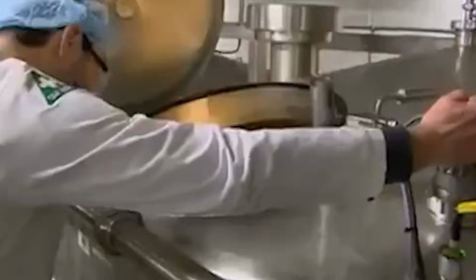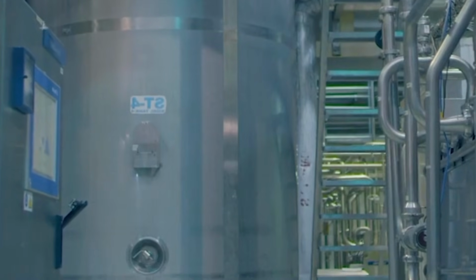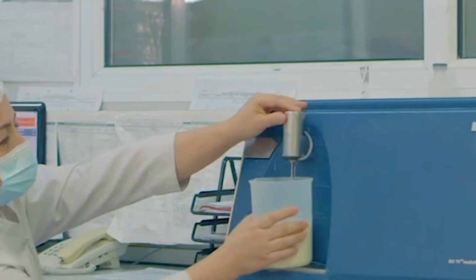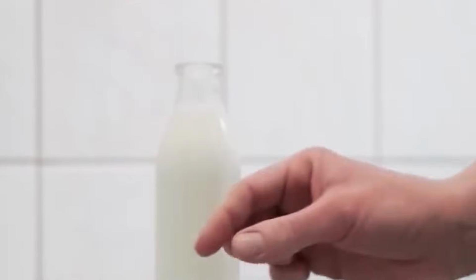The air injection rate is precisely controlled using mass flow controllers and synchronized with product flow rate. The resulting product exits the freezer at a temperature of -5 to -7 degrees and has a soft serve consistency. If inclusions such as fruit pieces, chocolate chips, or granola clusters are required, they are introduced at this stage using rotary feeders or auger-based inclusion systems. These systems are calibrated to dispense particulate matter based on mass or volume per unit of frozen yogurt. Inclusions are mixed gently into the flow using low shear blending heads to avoid damaging texture or shape.